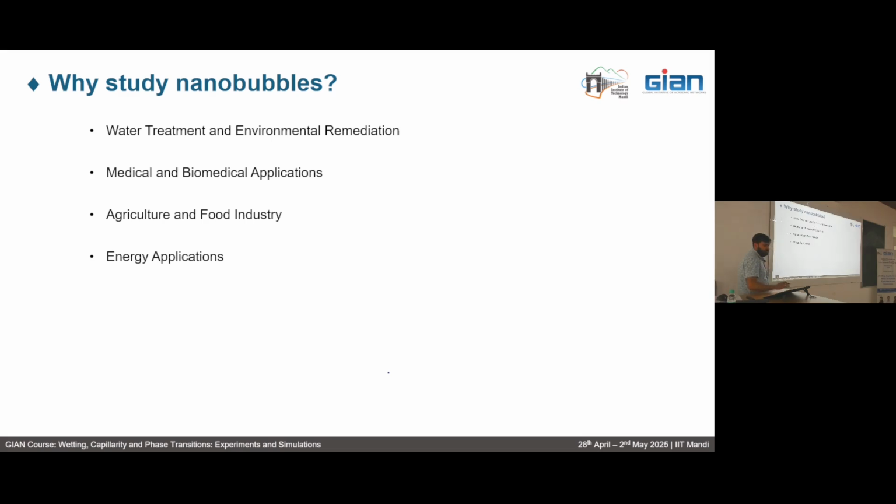It is being said, or almost proven by some experiments, that early nucleation occurs because there are nanobubbles on the surface, especially in hydrophobic cases. So in hydrophobic cases, we have an early onset of nucleate boiling. That is because gas nanobubbles act as cavitation sites for vapor bubbles to grow. So this is one application. In energy, there are also some papers which prove that the microdroplets which are formed on a surface are also because of the nanobubbles.